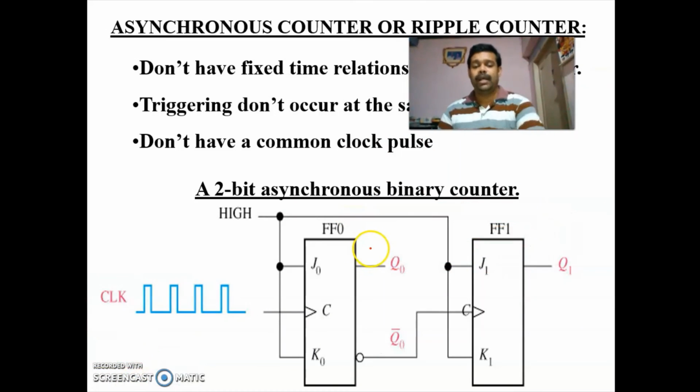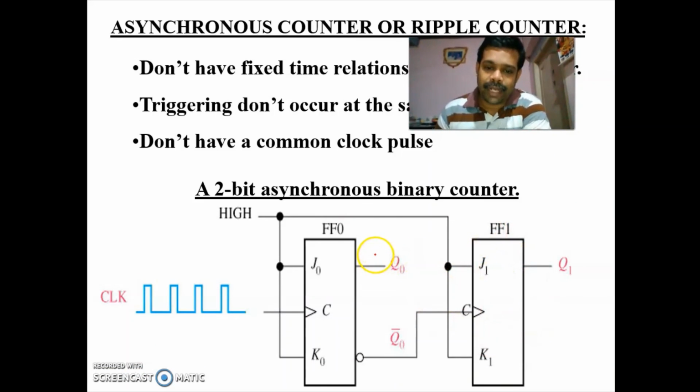explain once more. So the second flip flop will conduct only when you are having an output of 0 here. Okay. Make the first point. Now initially both the outputs are 0. And this first flip flop f naught will change the state during every positive clock edge. This is the first positive clock edge, this is the second, this is the third, and this is the fourth.